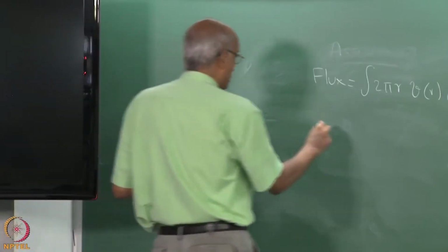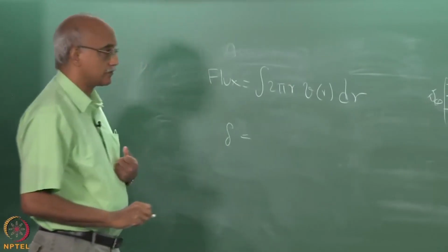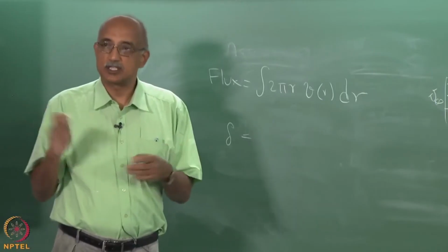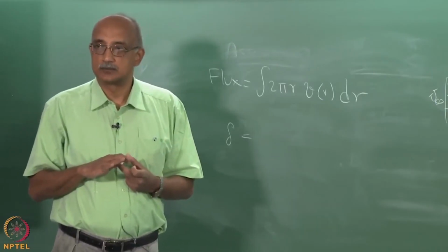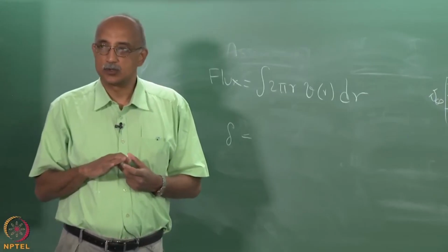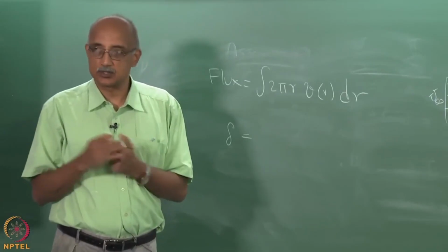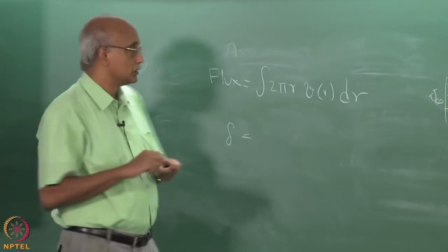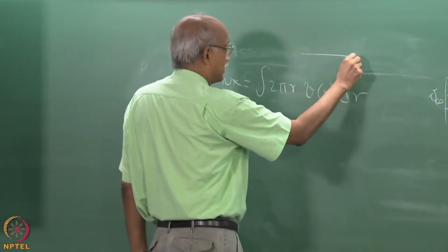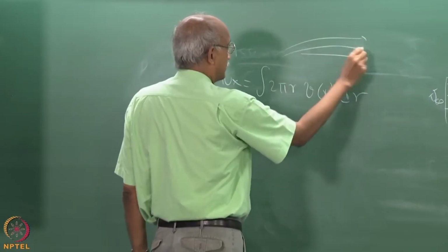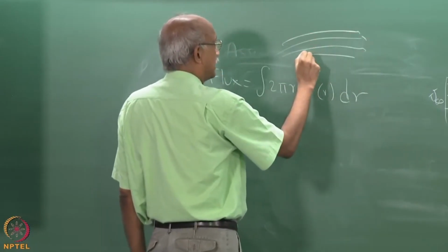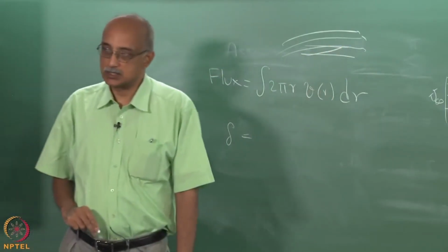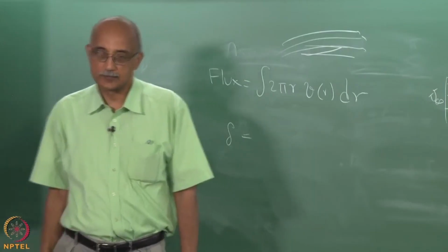The variation of the boundary layer thickness as a function of x distance is what? I mean, what will be the dependence of boundary layer thickness on x? Does it go as delta proportional to x, or x squared, or x to the power half? See, we are talking about a flat plate, flow past a flat plate, right? And so, we are trying to understand how this boundary layer thickness will change as a function of downstream distance x.